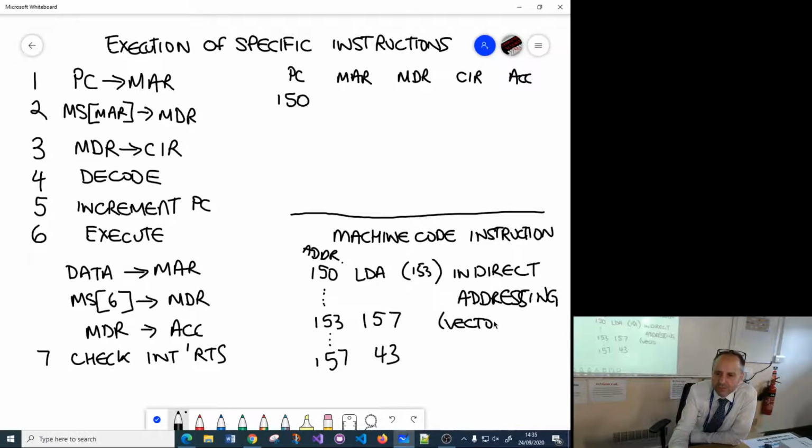And it comes from interrupt vectors. What this addressing mode allows a hardware manufacturer to do is to specify a specific fixed location where the program counter will get set to in order to carry out a specific task when an interrupt occurs.